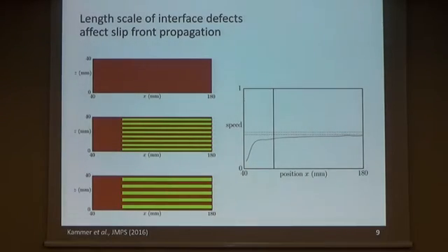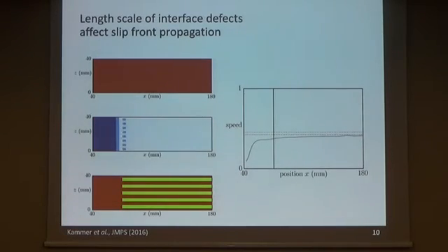Now I show you two cases with the same material properties, the weak and the strong. In both cases, 50% weak, 50% strong. So the average is the same. Globally seen, it's the same behavior. If you look at what's happening, you can see that it's propagating over here. It started, and then when it came close to the weak areas, the bump that is ahead causes a little daughter crack to be created in the weak area, and it tries to pull the main crack to super shear transition, but isn't capable. As you can see, actually it separates again.